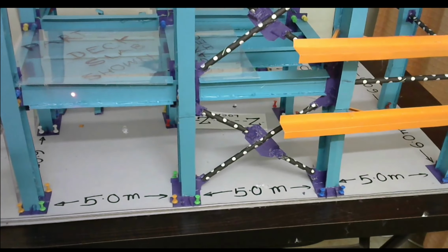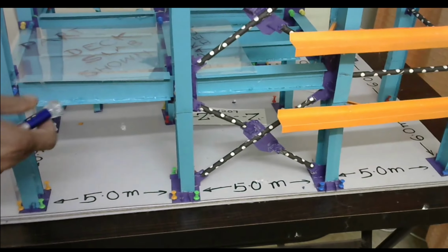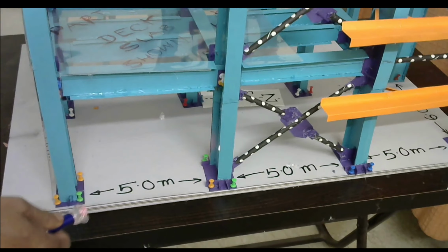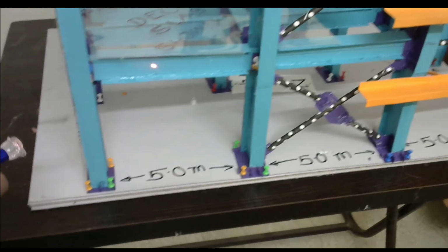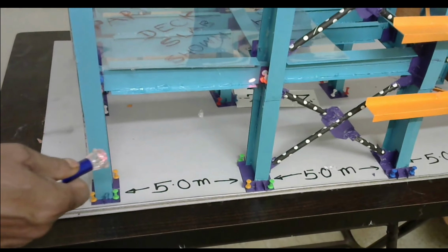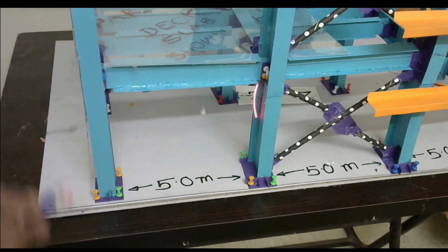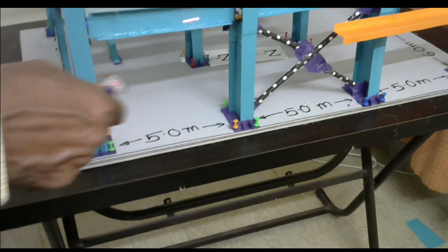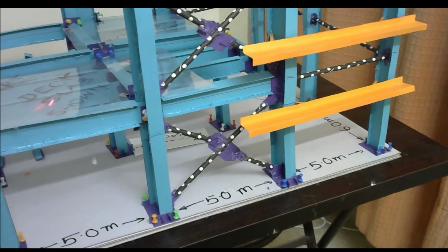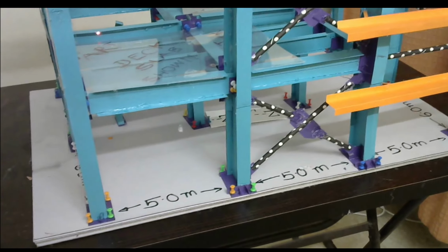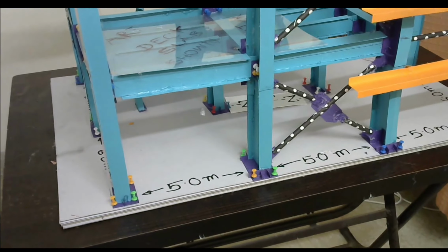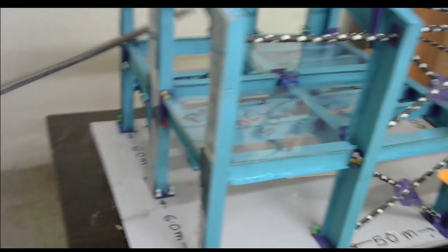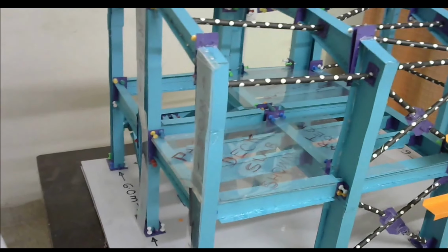See, I am taking LZ as 5 meter. It cannot sway along the vertical direction. Obviously, there is a steel foundation there, so we can always consider it is non-sway. It is braced against the vertical direction. Sway is prevented along the vertical direction. So LZ is 5 meter. Same is the case for the joist as well. If you consider this beam, this is also simply supported. This is also simply supported. So all these beams are simply supported. So we can consider this.